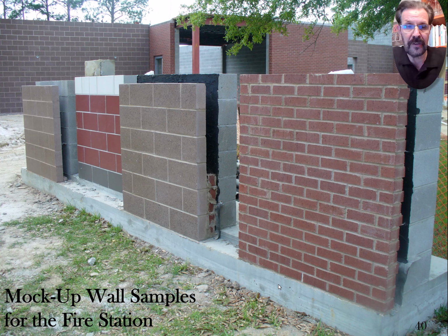And what you're looking at here in the picture, the first one that's closest to us on the right is a brick wall, and it's got a space between the wall, about a 4-inch space. You can see the waterproofing on the concrete masonry block wall, the concrete masonry unit wall. And then the next wall over, the sample wall mock-up, moving toward the left, those are marble stones. Those are cut marble pieces that are being held in place. And so it's everything about the brick ties too, and how the ties tie from one wall to the other, from mortar joint to mortar joint, and that sort of thing.